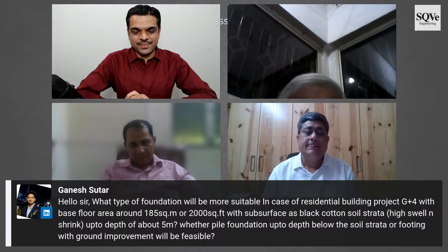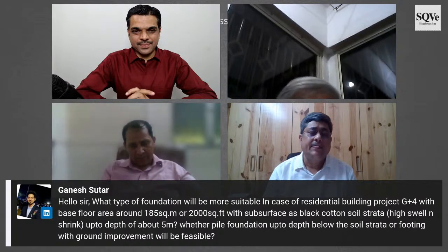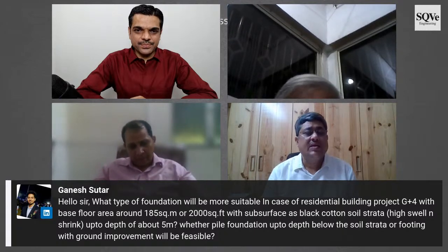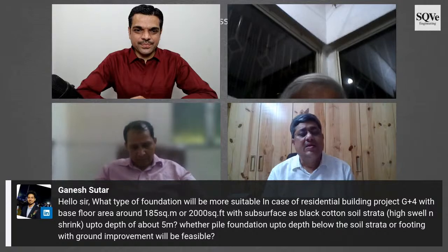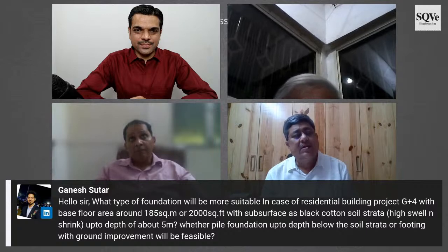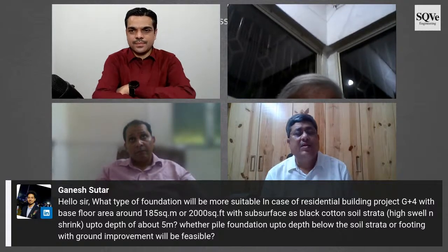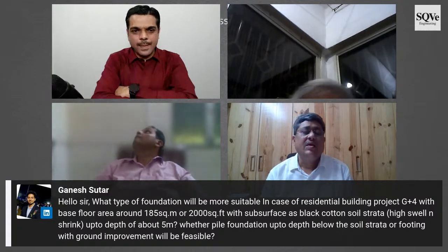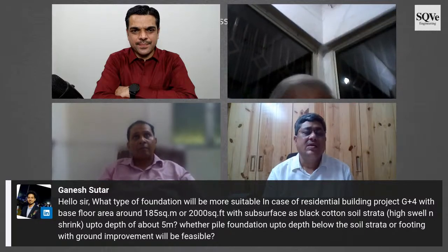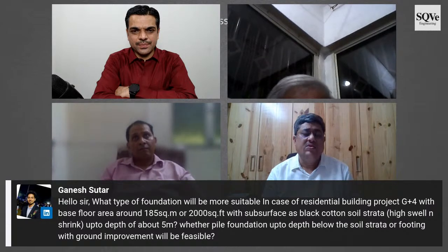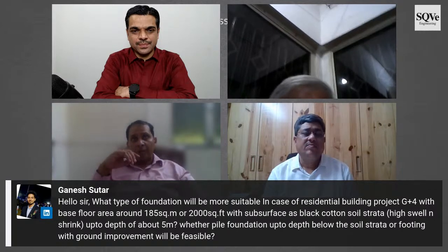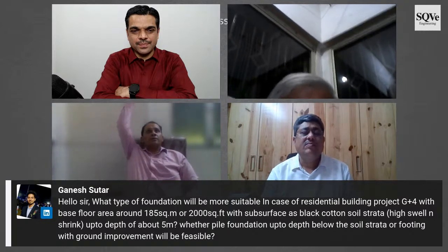I was just thinking about what was said regarding the collapse. It depends upon black cotton soil's characteristics. When you make a bulb under the piles, essentially that underream arrests the uplift because of the swelling pressure. But if that bulb were not to form, the load transfer because of cohesion would still take place. That was one area where Sandeep can correct me, but what you said is right. Sometimes it does happen like that.